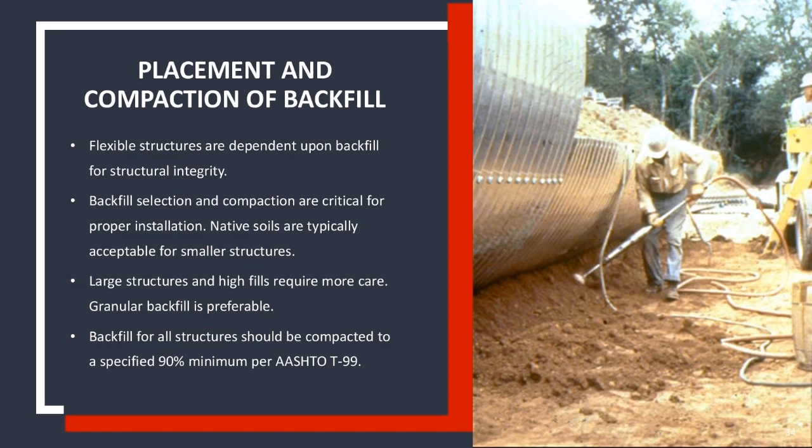I try to keep my opinions out of these things as much as possible, but really, when I start to get up into the 5 foot, 6 foot diameter pipes, is when I'm really going to start thinking about a finer granular or stone backfill to make sure that those haunches are truly supported when you get into installation. Like I mentioned, larger structures and higher fills are going to require more care, and that's when you really want to start thinking about a granular backfill. And then backfill for all structures should be compacted to a specified 90% minimum per AASHTO T99.